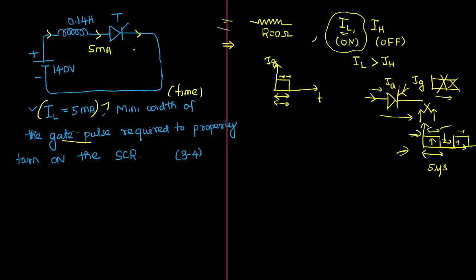It's beautiful. Now, how do I figure out that time period? So let me tell you. When you have only an inductor, figure out the relation between voltage and current. Keep this in your mind: in this given circuit, how are we fixing this time period? It will be fixed by the inductor because the inductor will not accept instantaneous changes. You all know that. So from that we can figure out how much time it is taking. In order to let this 5 milliampere current through, the inductor will slowly allow the current to reach the maximum value.